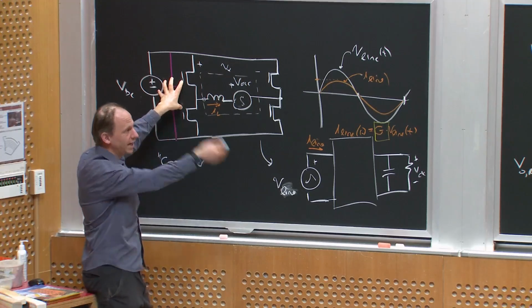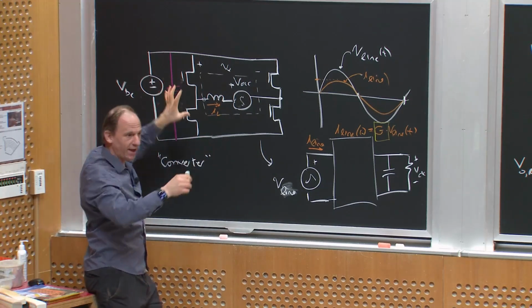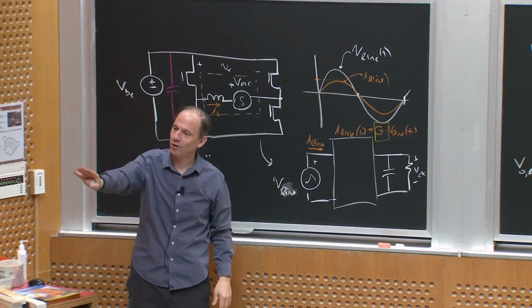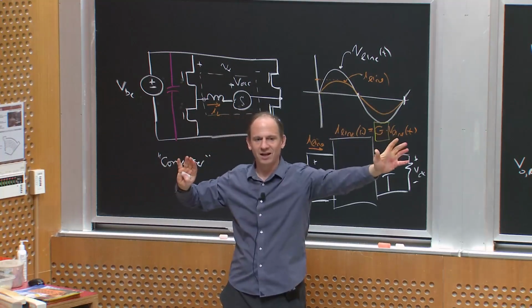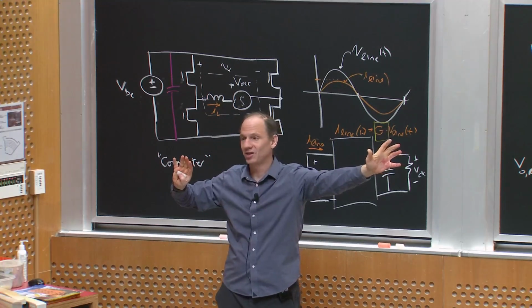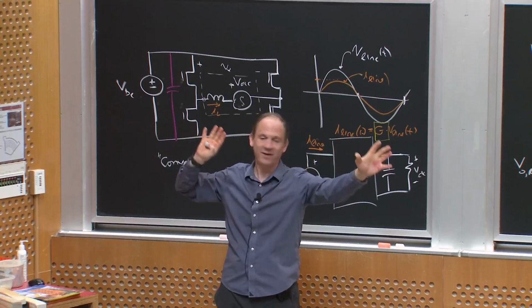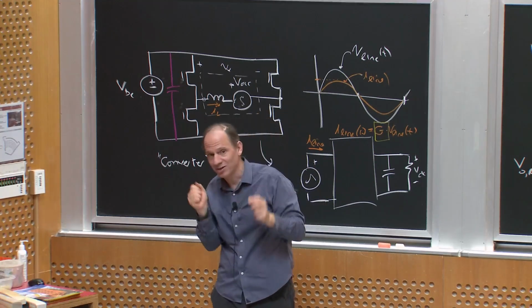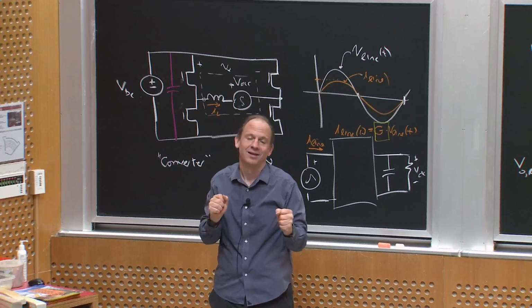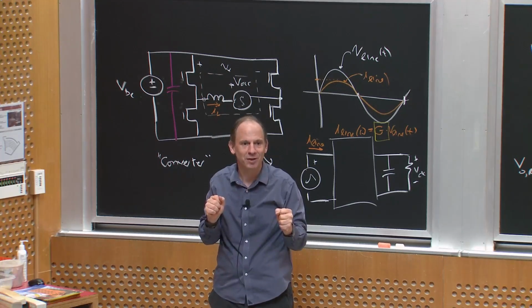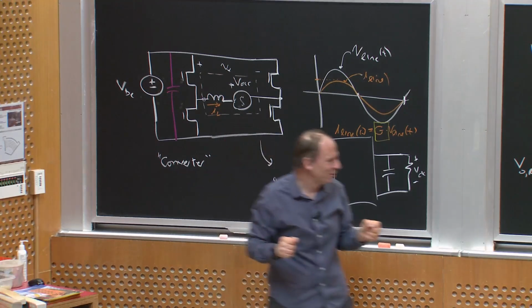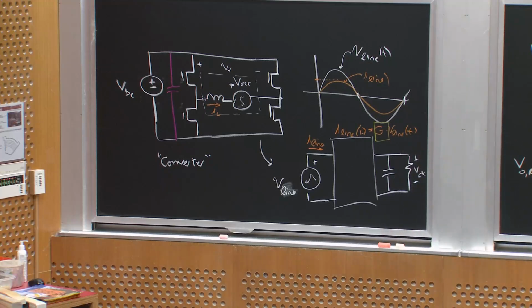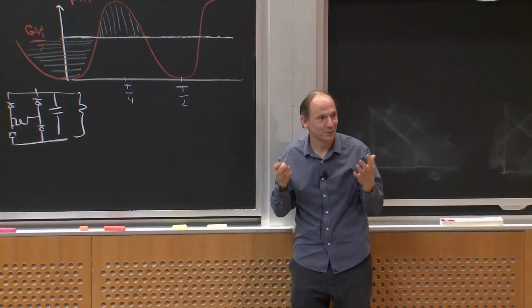So whether I'm going AC to DC or DC to AC, if I have pure DC power flow on one side and unity power factor AC on the other, there is no way around the fact that I've got to store some energy somewhere. And you'll find people that say, I've got this magic technique that's going to do it, except that conservation of energy rather forbids that, right? No, you don't, because conservation of energy holds.